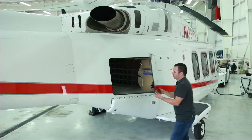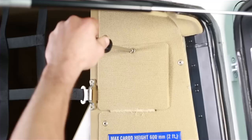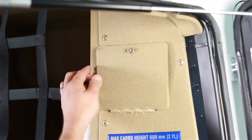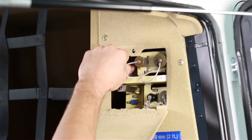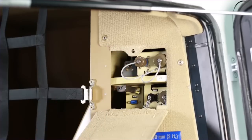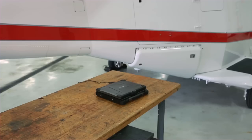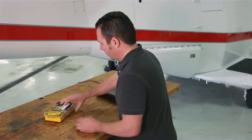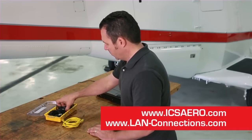We'll show you how to update databases on an AW139 helicopter equipped with a Primus Epic Avionics system. These procedures are applicable to all Primus Epic AW139 helicopters. To perform this task, you'll need the database updates, a remote terminal, and an interface kit like the LandTap 10. If you don't have one, you can order it online from ICS Aero or Land Connections.